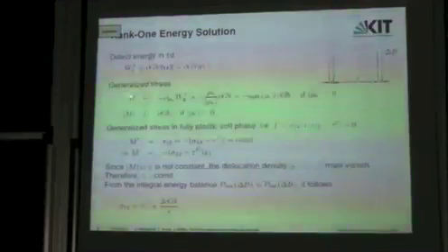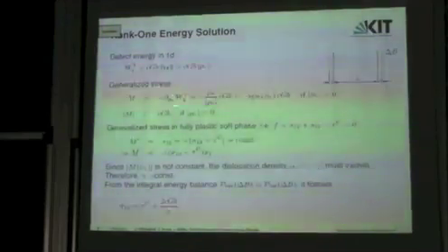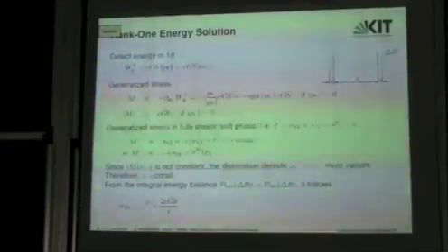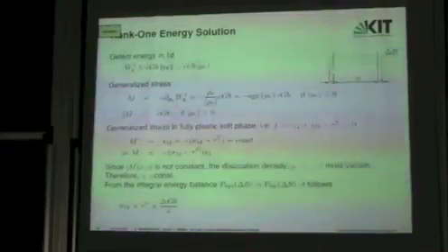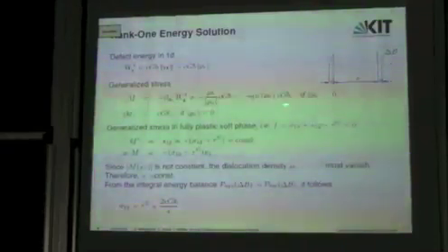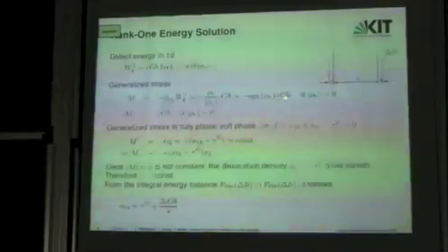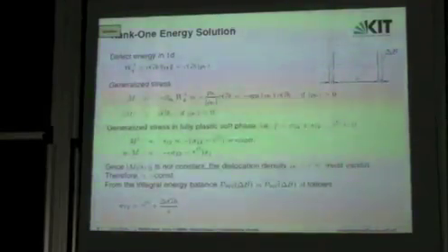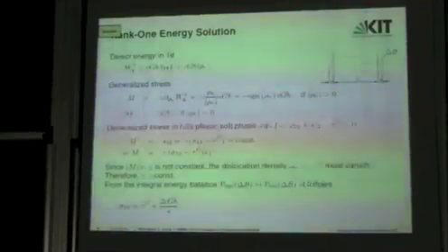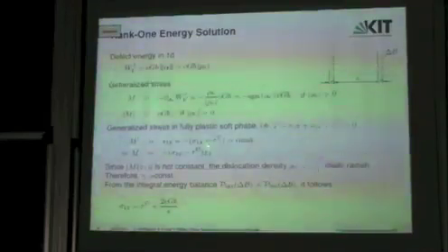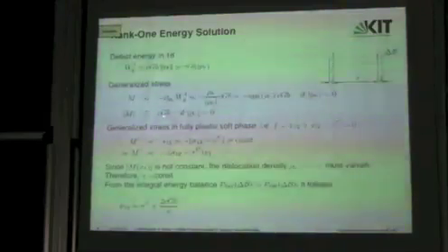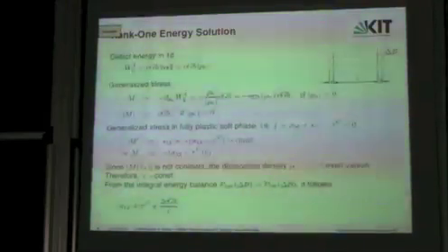We start by evaluating the generalized stress M simply as the derivative of the defect energy, and we find that if the GND density is not equal to 0, then the absolute value of the generalized stress is given by a constant C_GB, and only the sign is determined by the edge dislocation density. Whereas if the GND density is 0, then M is less or equal to C_GB.